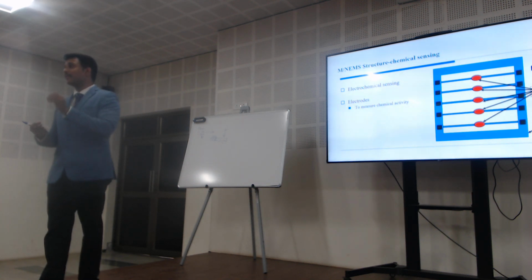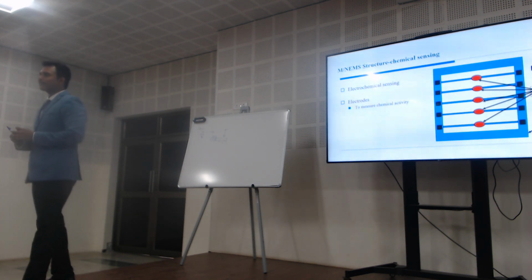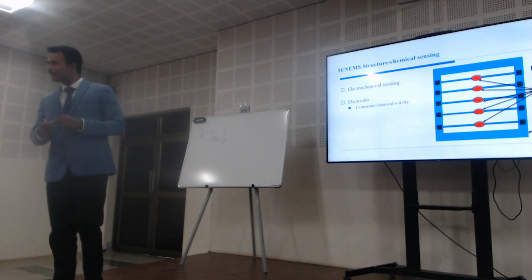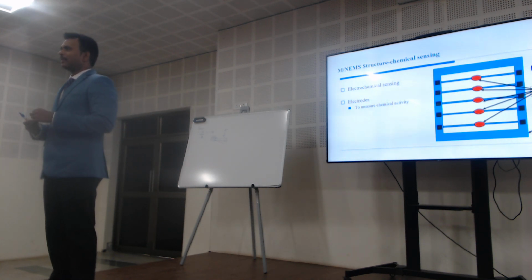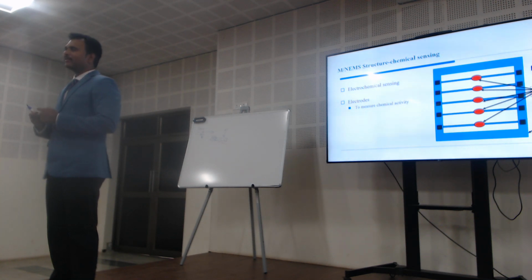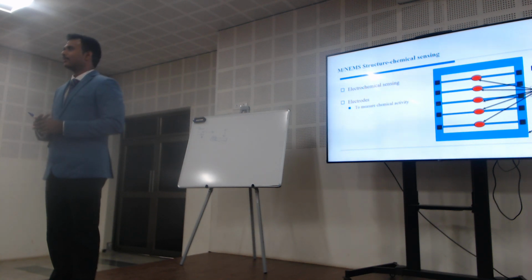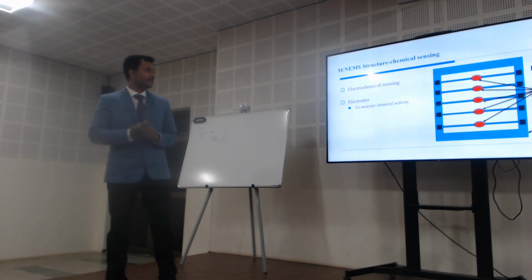Capacitance MEMS have very good sensitivity compared to piezo MEMS. And one more thing, piezo is an active sensor only, but there we get a very small electrical value. Sometimes we cannot process it with the electrical circuit. So that is one of the major disadvantages of that.